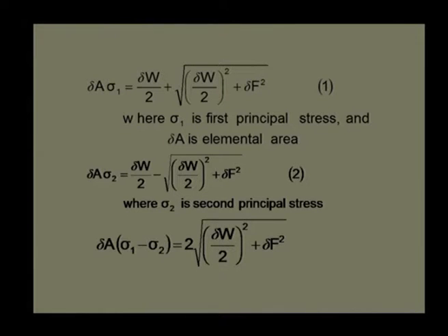So we subtract and we get an expression something like this. You can see there is a normal force divided by 2 plus tangential force, and this is sigma 1 minus sigma 2, which I am saying should be equal to, or the minimum value of yield strength should be equal to this. It can be more than that, but the minimum value should be like this.